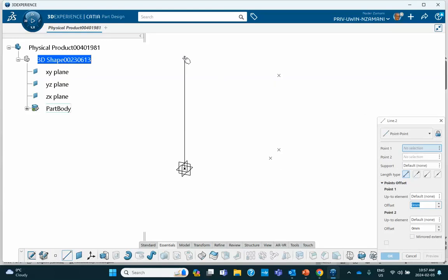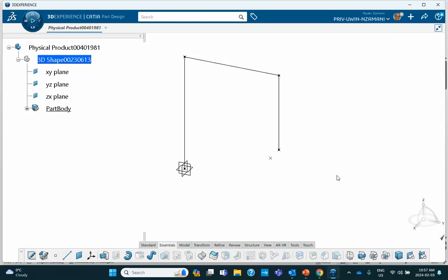This is going to be the beam, the horizontal beam. And this is going to be the vertical column on the right side. The column on the right side. And okay, and then we cancel. Notice that if I join these three in the generative shape design and mesh it, there won't be a problem. There won't be any duplicate nodes. However, I'm not going to join that.